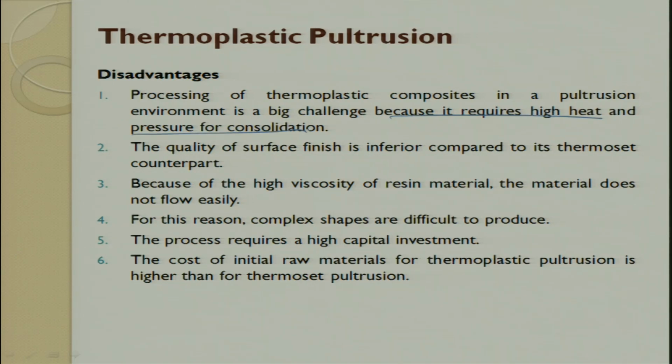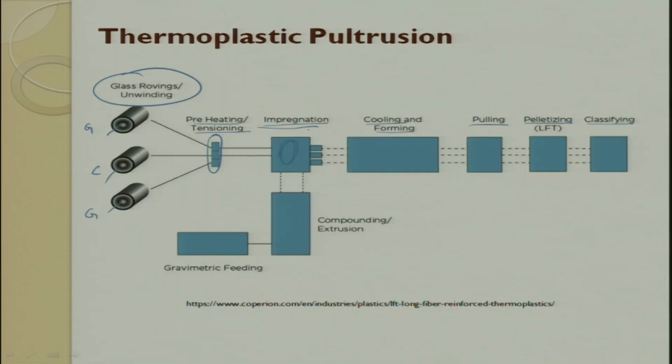Here I have missed out a point. Here what we do is we give the forming, whatever I said here. Here is where we keep a die and we try to maintain the cross section. So, cooling is done and the cross section is also done, so that you can get a square or rectangular channel, rectangular box channel, circular shaft, gear. In fact, interestingly, you can also get a pull-through star for some applications like this.